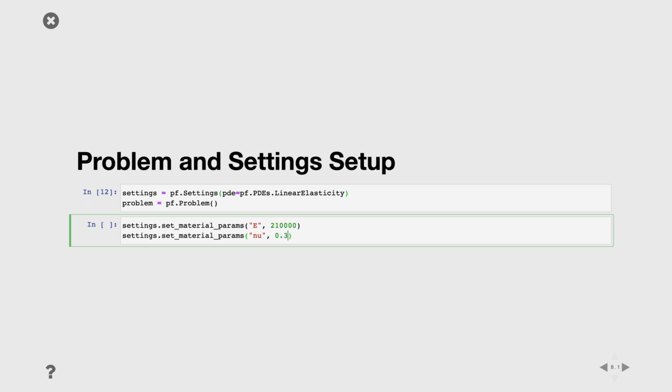Here I want to do just a tiny parenthesis. If you don't know about the material parameters, it's fine. Just don't pick something random, because some are not physical, so you will get garbage out of it. If you know about material parameters and what they are, you also know they have units. The whole library Polyfem is unitless, in the sense that you need to be sure that everything is consistent in the correct unit. So if your mesh is in meters, you need to be sure that your material parameter is also in the corresponding unit. The unit is not really important as long as everything is consistent with each other.